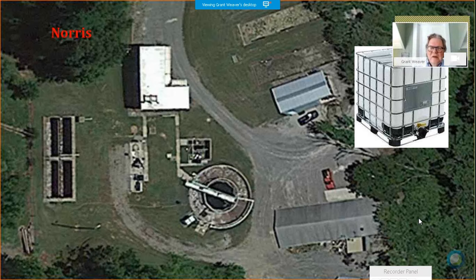So the plant staff there found a couple of used chemical totes, 300 gallon, 250, 75 gallon, I'm not sure which size they got, maybe 350 even. But 2 of those chemical totes, and they waste sludge into it. The sludge sits there for a couple of days, maybe a little more, and then they drain that sludge back into the aeration tank. They've created a side stream fermenter for $100 that takes mixed liquor, lets it go